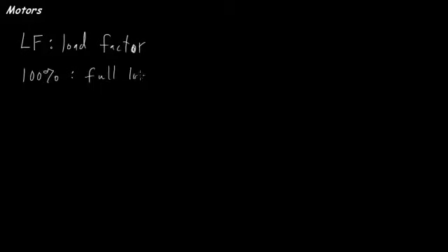Okay, another important characteristic of a motor is what's known as the load factor, abbreviated LF. This is basically a percentage that measures how hard the motor is working compared to its full output. So if my load factor is 100%, then my motor is working at full load. So basically, load factor in terms of an equation is my power output at partial load, PL, divided by my power output at full load.